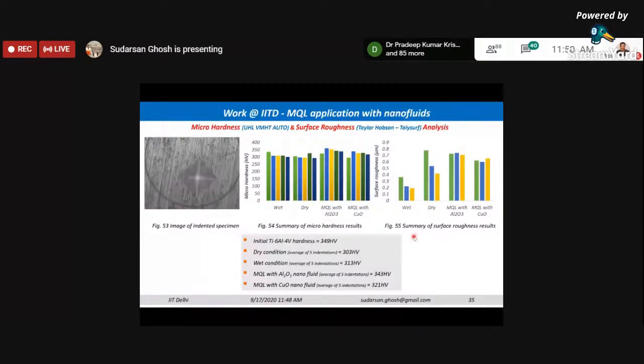grinding process. Now here I would like to let you know that the grinding wheel abrasive size which we have used is not supposed to be the abrasive size used for a very smooth surface finish. If we really want a very high surface finish, we have to use a very low grit size. Whereas in our experiments we have used a moderate grit size, which has the capability to remove more material rather than giving a better surface finish.